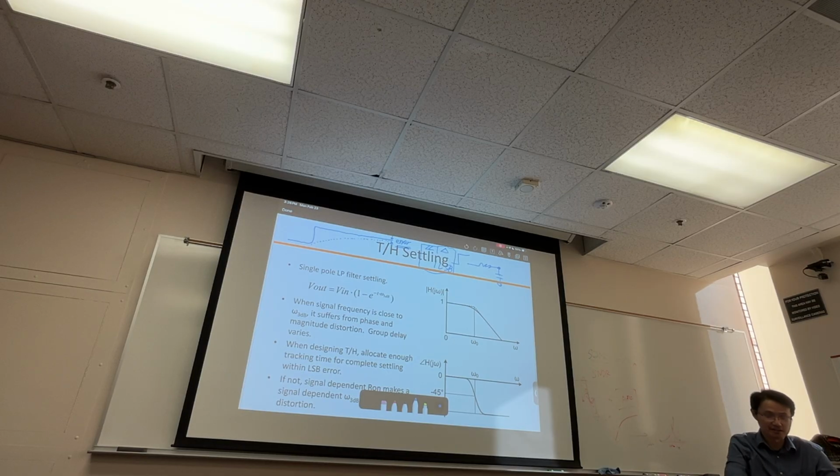If that's much less than the conventional noise power, that means that your actual SNR will be fairly close to your SQNR. Do you agree? Which means that your ENOB will be very close to N. Does that make sense? Your ENOB is computed from your SNDR. Right? So you see they are all tied together, right? So that indeed is the rule of thumb.